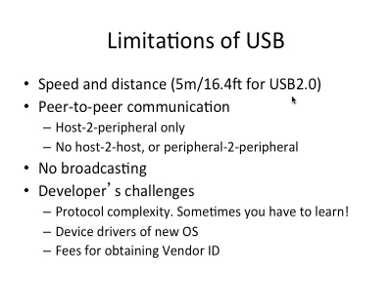For peer-to-peer communication, it supports host to peripheral only. You cannot do host to host or peripheral to peripheral. That means you essentially have a master or host device, the host controller, and then peripheral devices. You cannot do broadcasting.